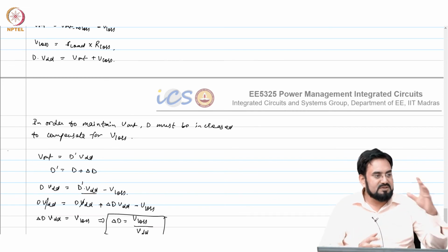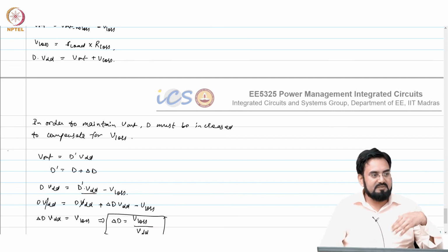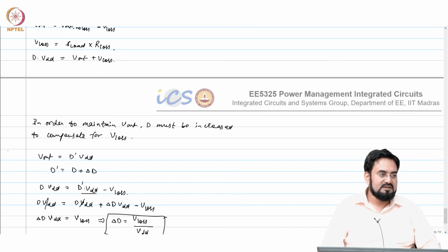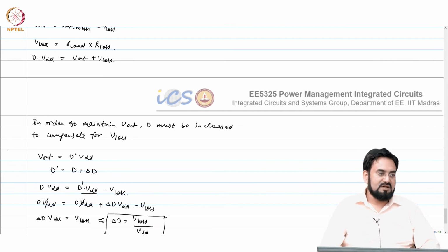So, you use a feedback control here, the negative feedback, and that is what negative feedback does. It varies your duty cycle based on changes in the R or load current in order to maintain the output voltage. And then you go back to the negative feedback compensation, all the concepts will apply here, because now in the loop you have an LC filter, which is a complex filter.